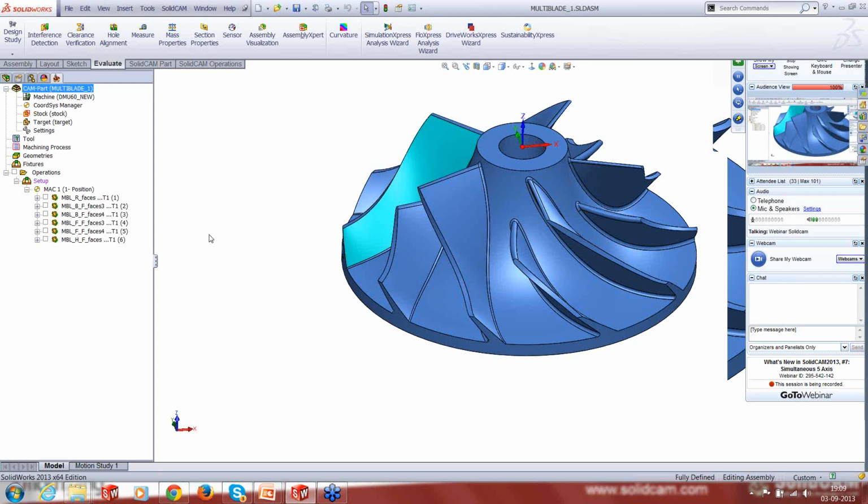Swarfing is using the side, trimming is using the tip, because you would like to dig into the surface when you're doing trimming. But in swarfing, you're actually not digging, but you're only going onto the side. So I would not think that you would like to use swarfing to do the trimming. I would still feel that you can use Contour 5-axis to do the trimming, unless you get into situations where Contour 5-axis can't really handle that geometry.